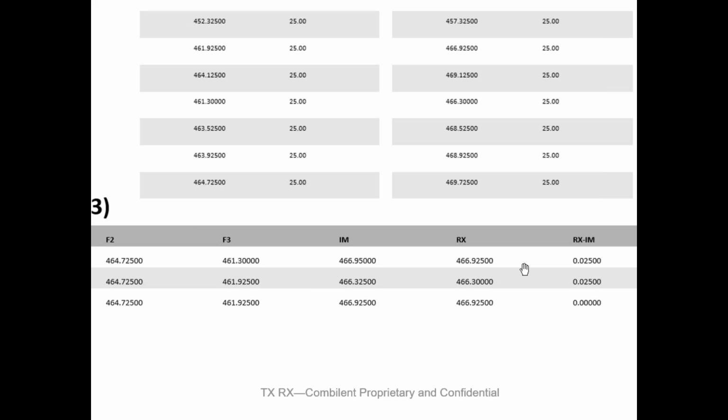And again, we'll discuss this with the customer, and we may be able to suggest some possible remedies. If there's more than one antenna, we could potentially move the offending frequencies, split them up between the antennas, or maybe the customer has a different frequency plan that they can provide for us to continue the design with.